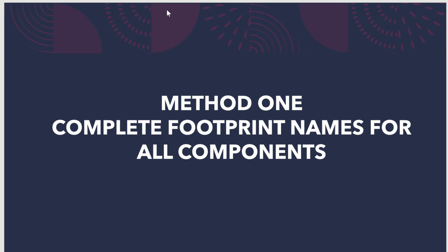First, create a board from scratch using technology template .tch. Second, create a board using a board template .tpl. Finally, import a third-party board to layout using Translator. Each method has its own purpose and benefit depending on how you plan to design your board.